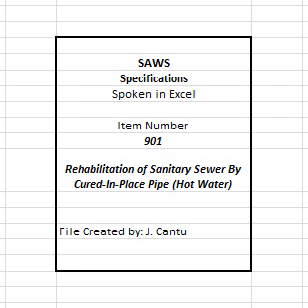Open cut excavation for service reconnect irons will only be allowed if it has been approved in writing from a SAWS inspector. Service reconnect irons shall be in accordance with item number 1109, sanitary sewer lateral stub outs or reconnect irons. Contractor shall provide all coupons removed as part of the reinstatement of service process to confirm that a, the appropriate number of service connections has been made, and b, no coupons were left in the pipe to create an obstruction.